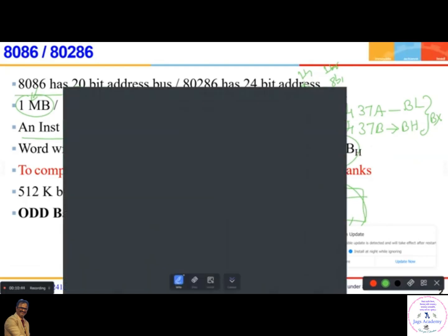Try to understand this before going into the actual topic. I'm just going to explain how we arrange the memory. Assume that your 8086 microprocessor can address how many memory locations? 1 megabyte locations, right? So for 8086 interfacing, try to understand each and every point which I am telling here. For the 8086 microprocessor, interfacing one memory chip of 1 megabyte will be impossible, right?